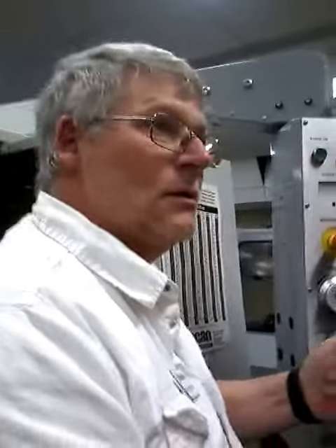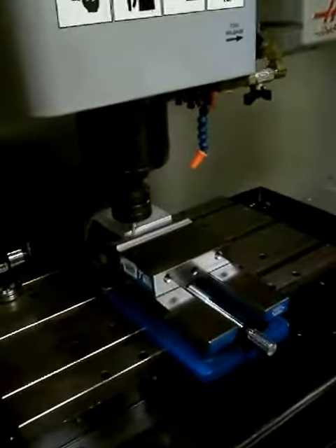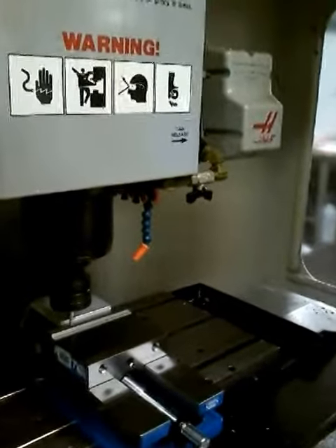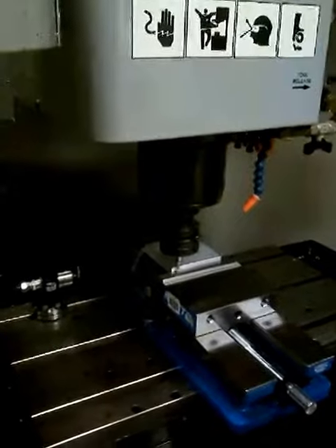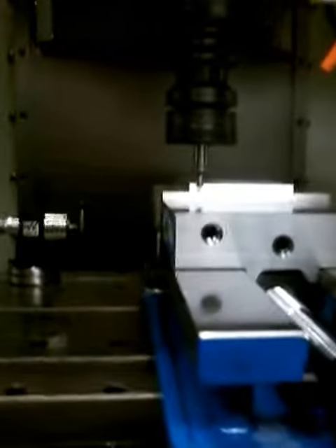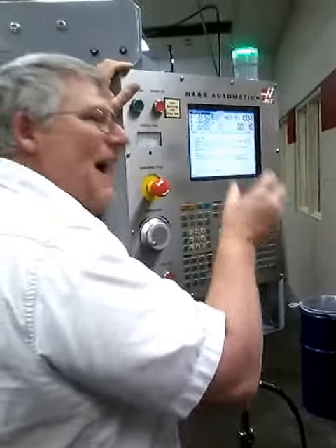Now I'm going to set Y. Everybody ready to set Y? Edge finder. Everybody knows how to use one. If I run it down into that, I'm going to break things. I'm going to choose not to. Slow it down. Watch for the kick. Everybody see it? I'm within a thousandth because I know when I move this one click at a time, I'm moving thousandths at a time.